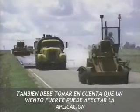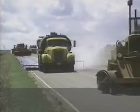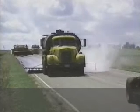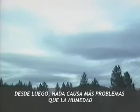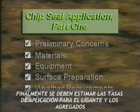You should also be aware that high wind can greatly affect the binder application, so don't apply the oil if the wind speed is excessive. Of course, nothing causes more problems than moisture, so the operation should not begin at all if rain is likely. Finally, you'll have to determine the application rates for the oil and chips.